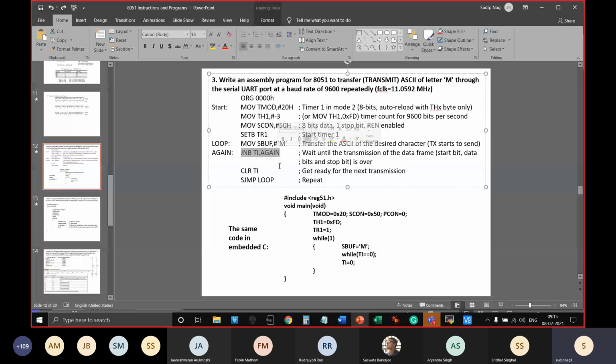There could be an interrupt method for the same operation. Instead of looping, you can simply go and do some other work with the microcontroller, so it can execute other code also. If you activate the interrupt, I'll tell you in subsequent slides how to use it, and you can use the same concept to replace this particular statement with a fully automated mechanism, and execute other instructions here instead of waiting, because waiting is a wastage of time.